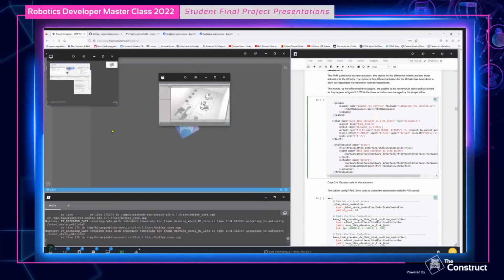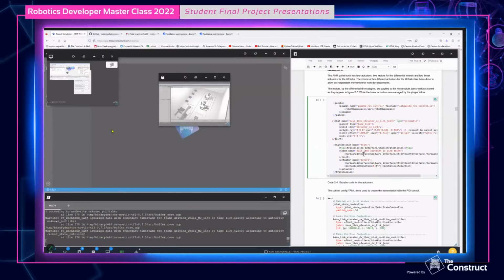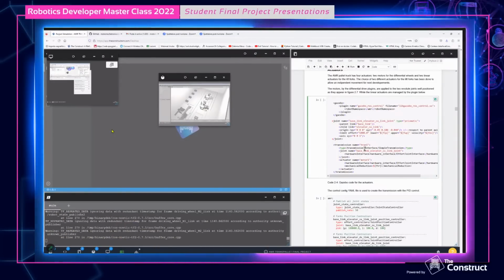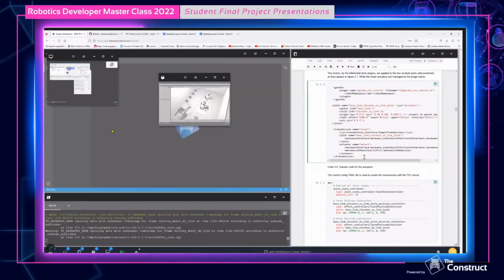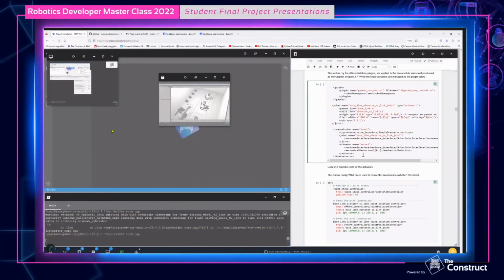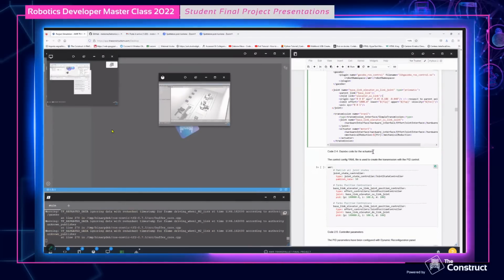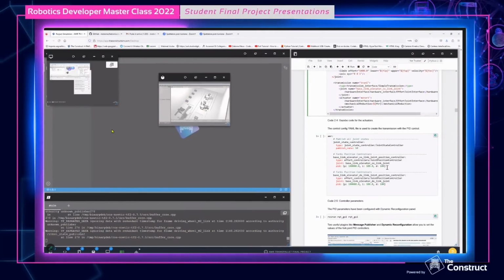The transmission is this, and the transmission is important to move the joint, so to move the frame. I used the motor, and I used a position controller that I found in the library. The position controller is a basic, simple PID.